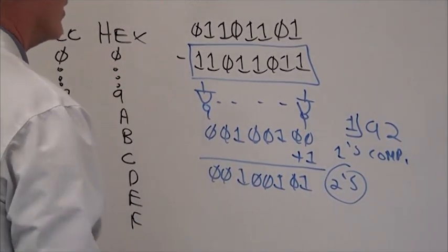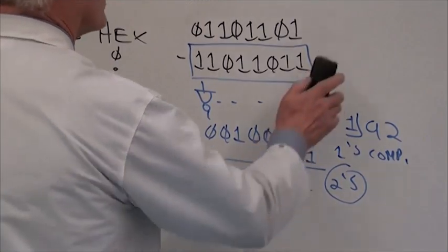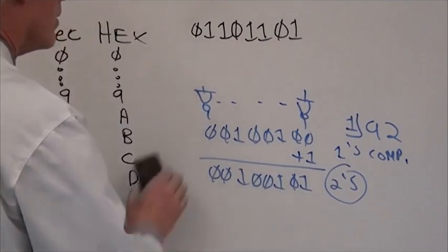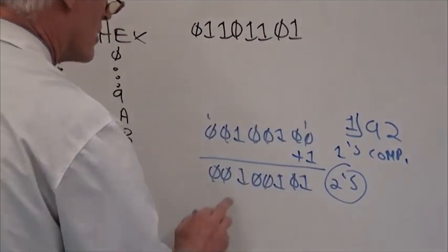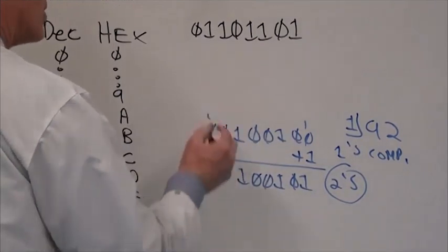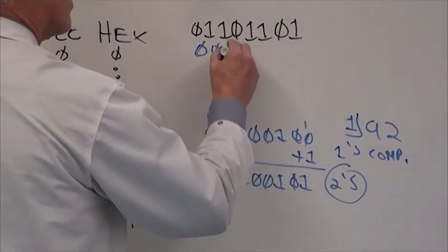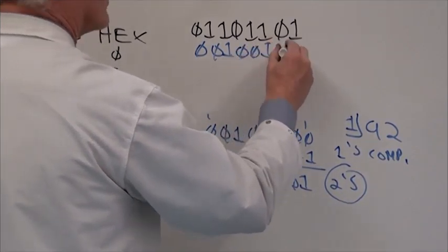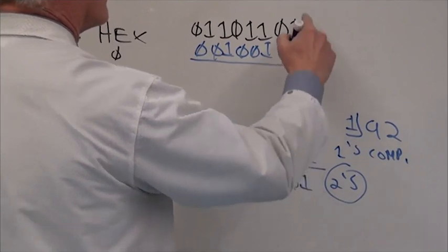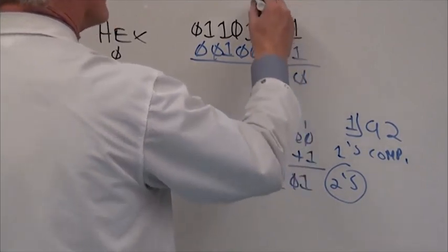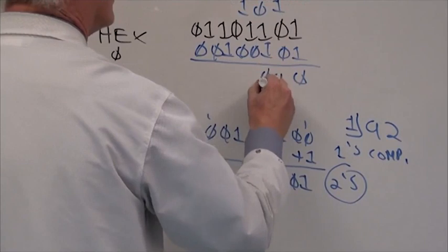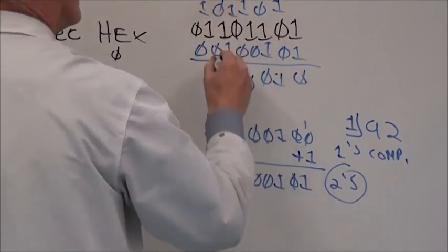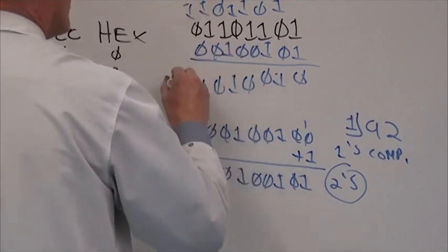Then what do they do? Well, they say, okay, let's get rid of this guy and turn the subtraction into an addition. So let's get rid of our inverters here. Let's take this number back and we're going to add that back to here. So this becomes 0, 0, 1, 0, 0, 1, 0, 1. And if we do this again, 1 and 1 is 2, which is 1, 0, and so on.